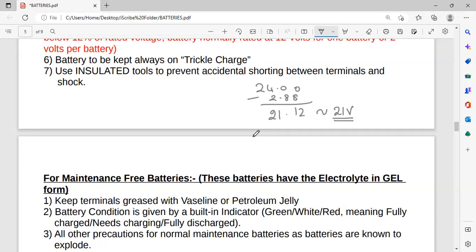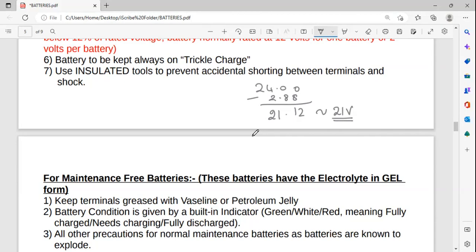Number two, such high heat is produced that not only do those two terminals of the battery get very seriously damaged, you will also notice that the tool you are using gets damaged. So please always take care whenever you are tightening those terminals. Insulate one of those terminals, put some insulating material between the positive and the negative, and then tighten the negative or the positive accordingly. Don't take any chances. This is one of the safety precautions that one has to take.